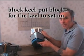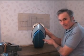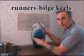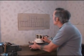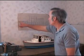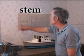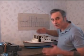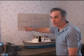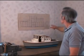This stringer runs down the middle of the boat. I'm also putting runners on the edges. They could be called bilge keels, but they're actually runners to support the boat on its bottom and to strengthen the bottom of the boat. At the very front of the boat, in the bow, is the stem. On the plans, this would be the line of the stem. The actual stem itself is a timber inside the boat that the two sides fasten to. It's fastened to the keel, and that makes up the backbone of the forward section.